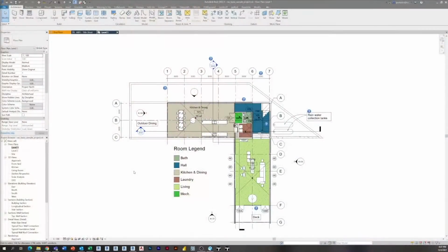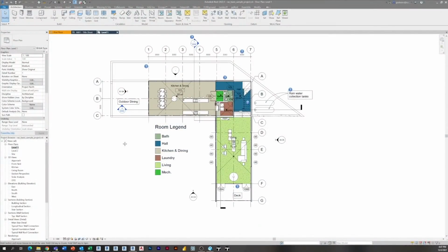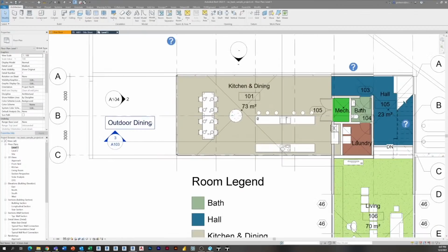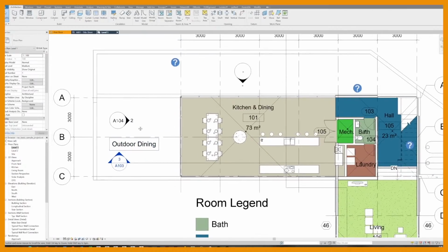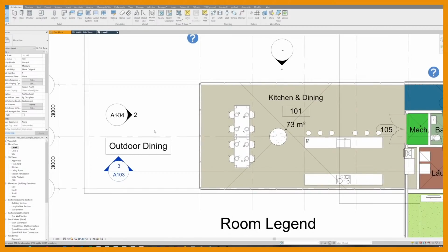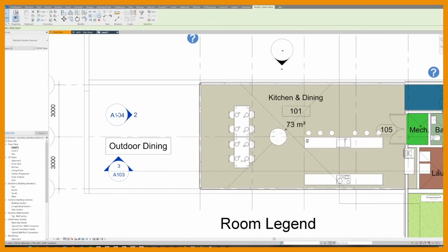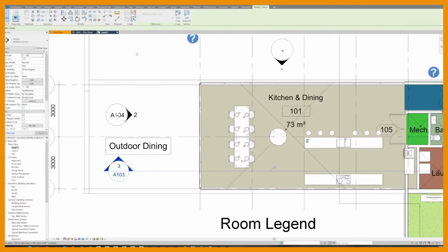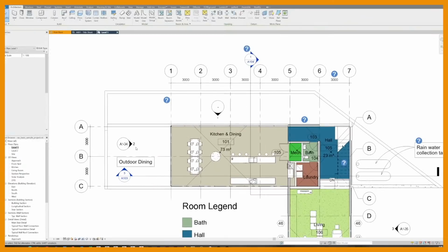It's an awesome, really quick tip that I think some of you will find super valuable. This tip is super simple, but pretty valuable. When you have elevation views and section views all set up exactly where you want them, and you don't want them to move, you can just select them and pin them. Select this section and pin it.